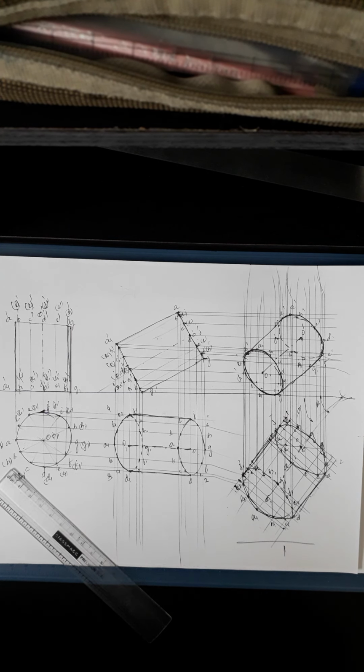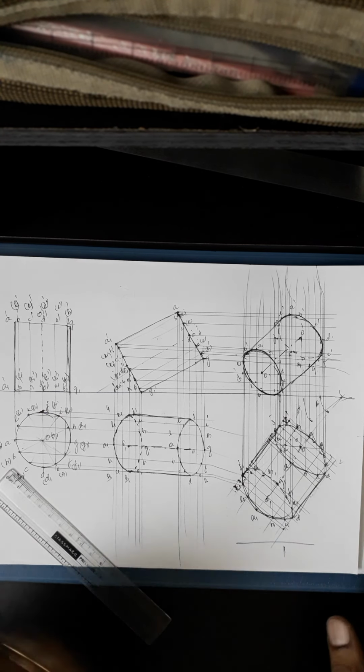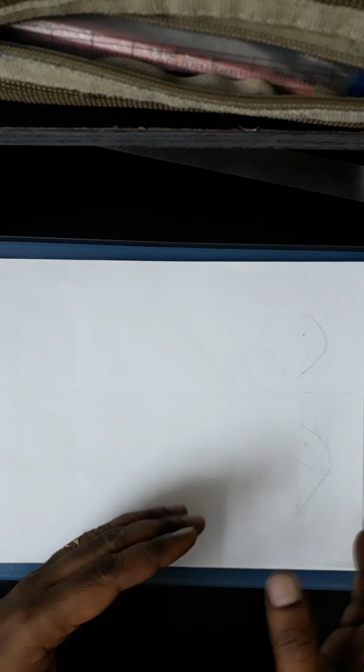The other problems that can be given in this will be, I will not draw the complete views. In this case, only inclinations; there's no edge of the corner, they're not going to give you that the edge resting on HP is inclined to VP. No problems like that, only the axis inclined to HP and VP. When they say 'and VP', they may be giving the 3 sentences. In that case, you need not take beta. Otherwise, if they say 30 degrees to HP and 45 degrees to VP, then you have to go for taking beta, because there is no 3 words given along with the VP inclination.